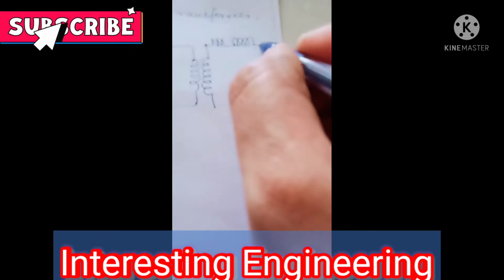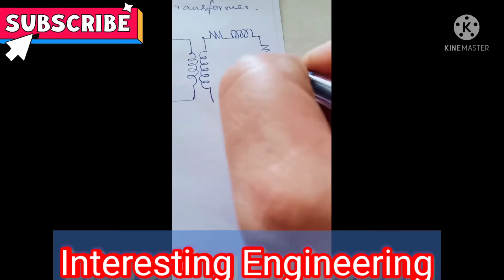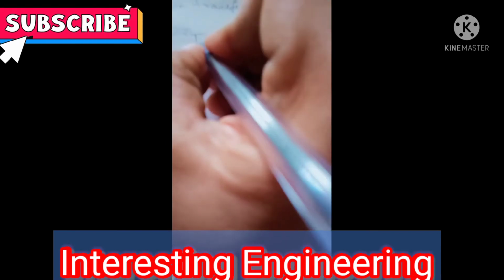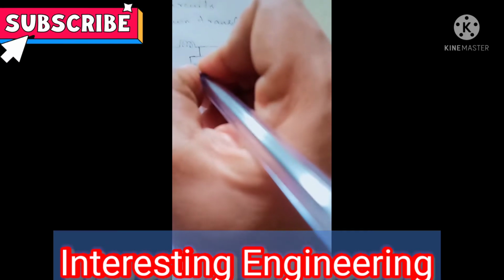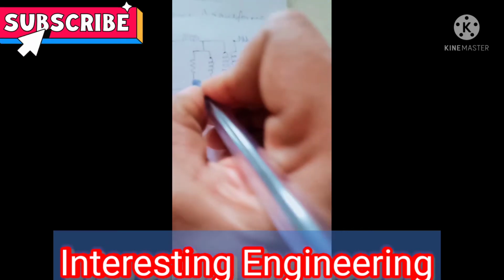This is the equivalent circuit, and here this is the secondary winding, and this secondary winding is connected with the resistance as well as the inductance. This is the impedance of the secondary side, and this is the impedance of the load side. And apart from this, we have a no load component denoted by IP, and so this is the equivalent circuit of a current transformer.